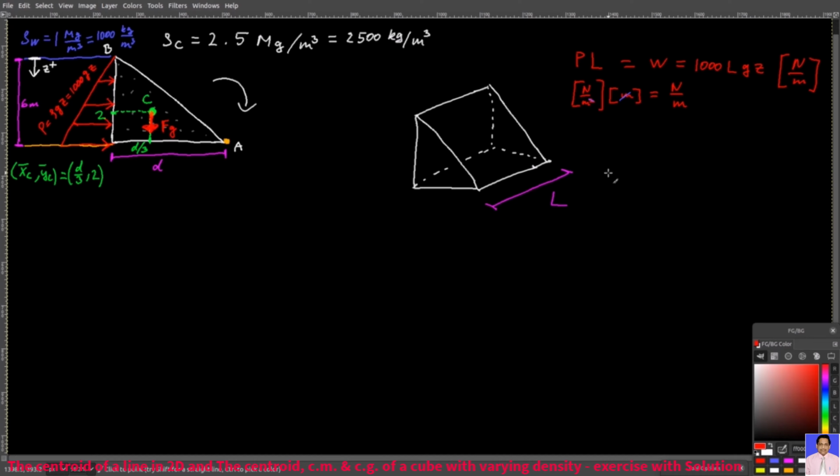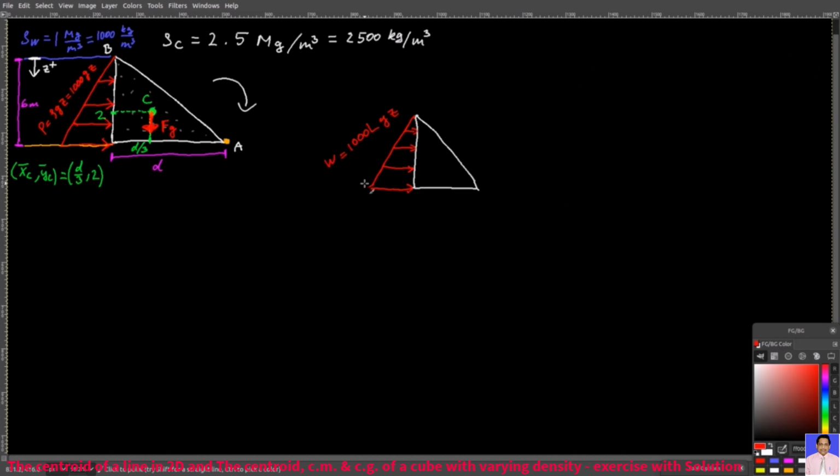And now here's the thing. The water will exert this pressure on the dam, and that distributed load has a center of pressure. We can equivalently represent this distributed load with a total point force Fw due to that distributed load that acts through this center of pressure.